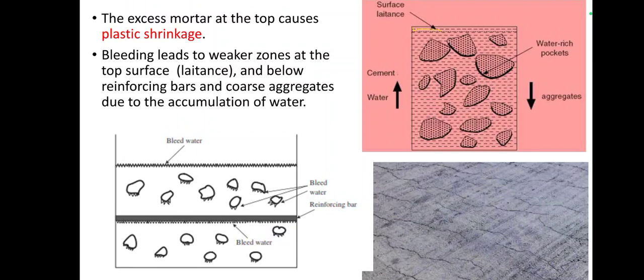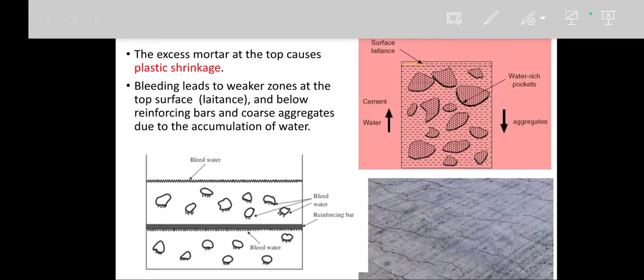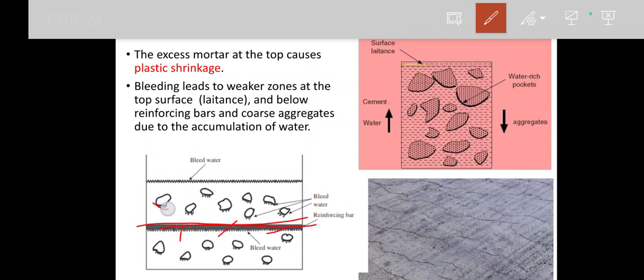If you add more water, it comes to the top surface and evaporates immediately. The evaporation happens very drastically when we make concrete during midday. So it will immediately form a pressure, and if restraint is not provided, it will cause a crack due to excessive stress creation. And also as I told, due to the bleeding, wherever the reinforcement is there, under that the water will try to get locked, or under the aggregate.